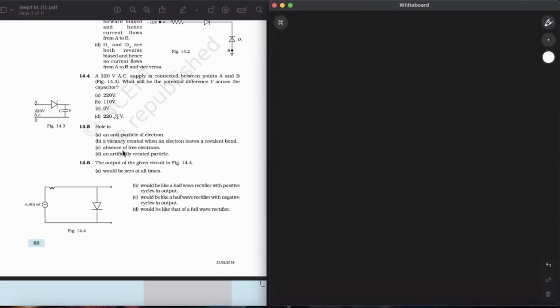Okay, so that hole is considered as a seat of positive charge because there is a vacancy of electron over there. So we consider that there is a positive charge, like a plus sign over there, because there is a vacancy of electron. You are getting my point. So these holes act as a virtual charge. Although there is no physical charge on it, there is no actual positive charge on these holes. We just assume that there is a plus sign over there because there is a vacancy of electrons.